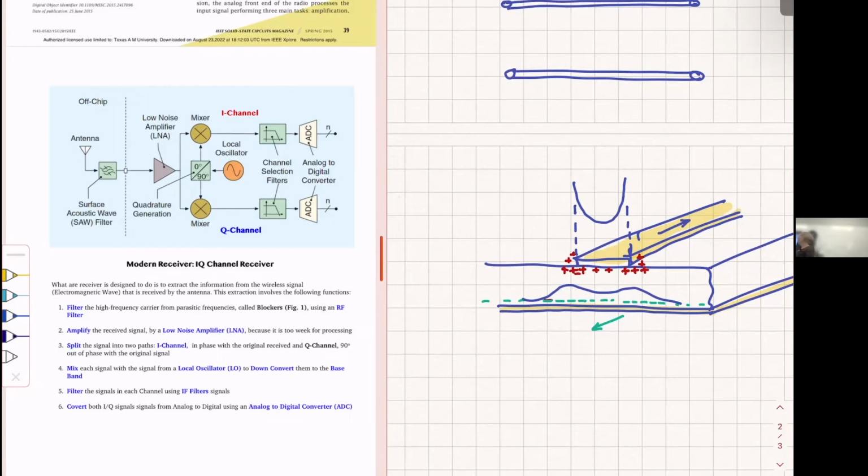But people moved away from this, as you will see, to some other structures. Why? Because I don't like these things that extend. What if I wanted to put another microstrip close to it? Then the current of the other microstrip underneath here and this one will mix up, and I will have what I call crosstalk. These are the kinds of things we'll see which are important in design.